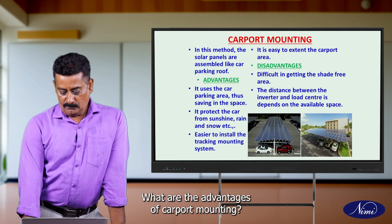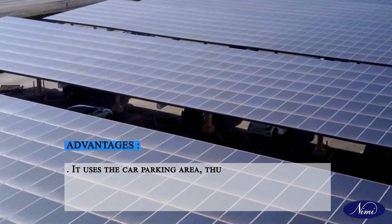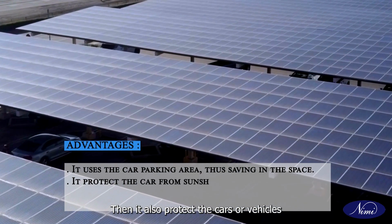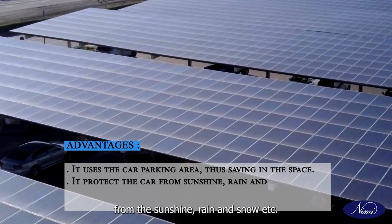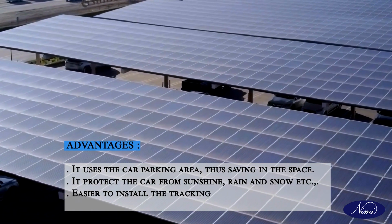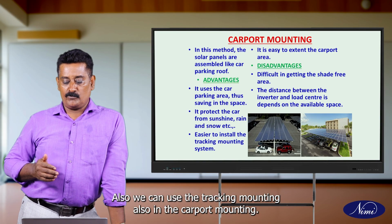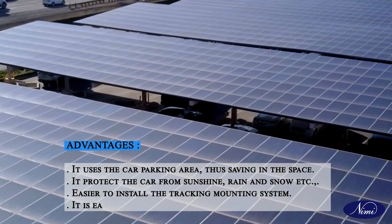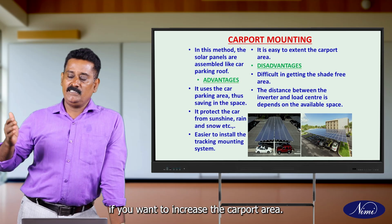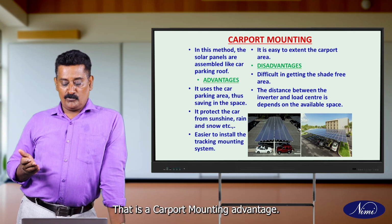What are the advantages of carport mounting? It uses a car parking area, so there is saving in space. It also protects the cars or vehicles from sunshine, rain, snow, etc. In this method, it is also very easy to install the tracking mounting. We can use the tracking mounting in carport mounting. The next advantage is that it is easier to extend the carport area. If you want to increase the carport area, we can easily extend it. That is the advantage of carport mounting.